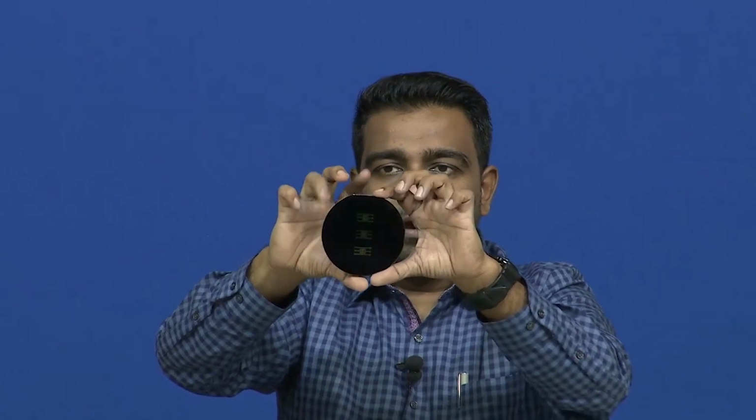The flat can be at 90 degrees as shown in this wafer, it can be at 180 degrees, it can be at 45 degrees, or it can be only one single flat. Now, the big flat that you can see here where my thumb is, this is a big flat, while there is a small flat right over here. So, we call them primary flat and secondary flat. The primary flat is bigger, the secondary flat is smaller. In some wafers you will only find a primary flat. Again, to distinguish the type of wafer and its orientation, we have the flats placed on the wafer.